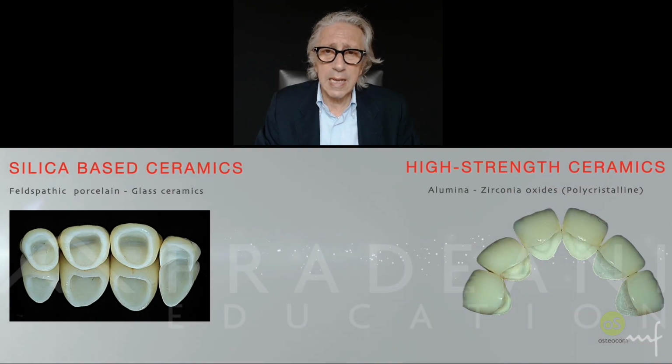First of all, we have the silica-based material, that is the lithium disilicate material, for example, or Empress material. They are glass ceramic materials, and together with the feldspathic porcelain, they are in the family of silica-based because we have the content of silica that is quite high. What is the main feature of this material? The main feature is for sure the translucency. Better to say, the light transmission property of this material that is very, very nice, similar to that of enamel and dentin.